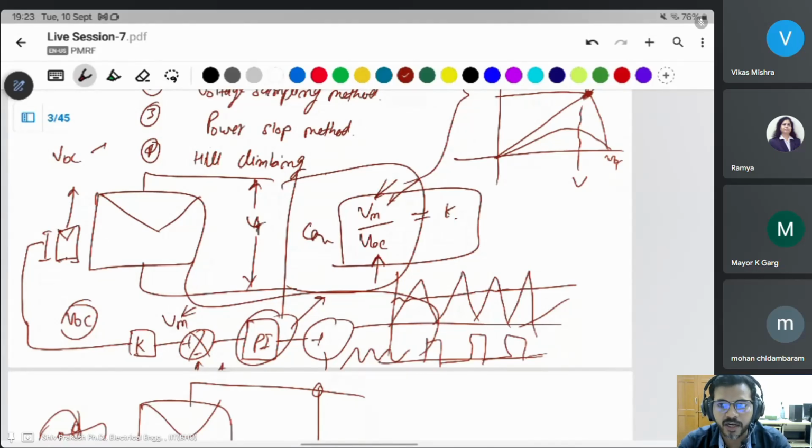If there is shadow, then you can't find it. So, sir, if the peak power is different for both, the reference as well as the solar PV, VOC is going to be the same? VOC is the same because the same voltage is taken, and VM will be the same for both at a particular time. That's why we take the same parameters of the panel, but with lower power of that panel. Okay, so same VOC and VM, but it will take lower power. Okay.